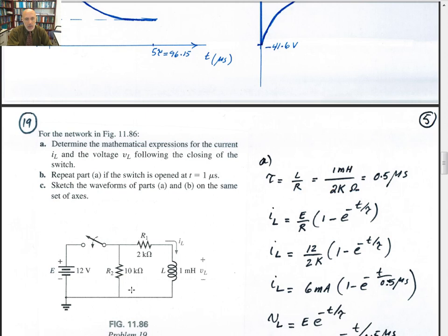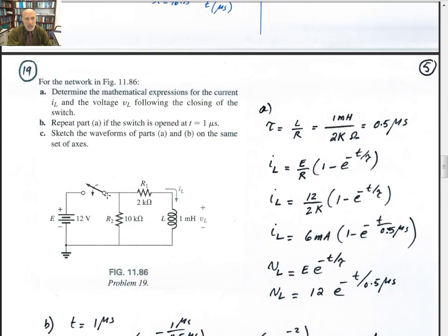If I look at these 2 points to determine the Thevenin, if you're looking back this way, if you short circuit this, then this resistor would be short circuited, so R Thevenin is simply equal to 2K. When you open the switch, it would be different, but during the charging process, the voltage here would be 12 volts. That's your V Thevenin. Then R Thevenin is simply equal to 2K. So when you calculate the time constant, when the switch is closed, this 10 kilo ohms is not going to come into the picture. It will not affect the time constant. So L divided by 2K, which is 1 millihenry divided by 2K, gives you 0.5 microseconds.